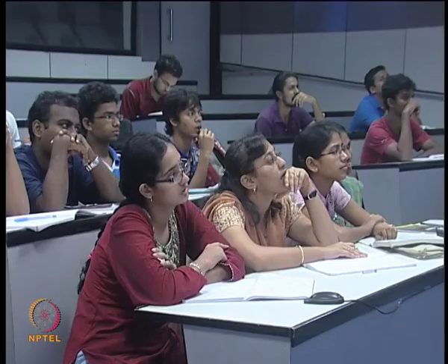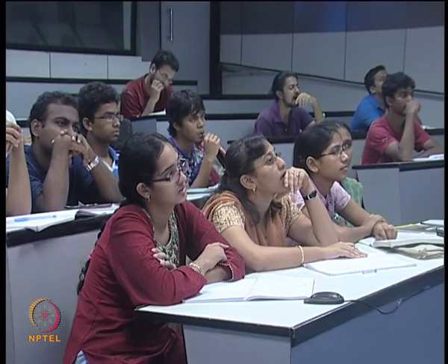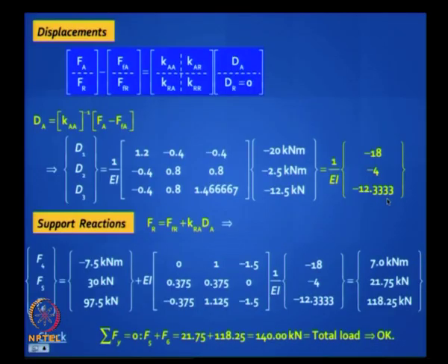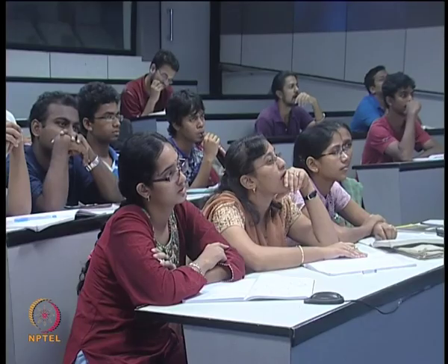You're familiar with this. Here you have to be careful about one thing. What is that? There's a Fi star F missing. What is it that you need to be careful about? The Di. If you go back, you got displacements D1, D2, D3, right? But when you go to the element coordinates, you have 4 degrees of freedom here, right? So you must get the correct Di relevant to the element that you are taking into consideration.